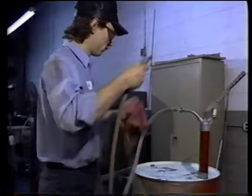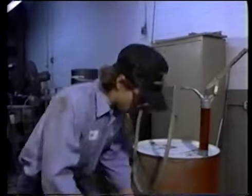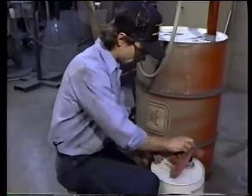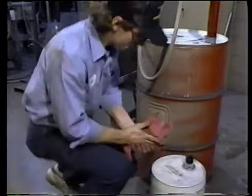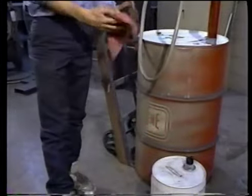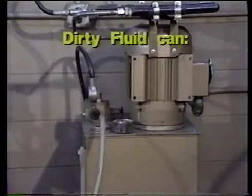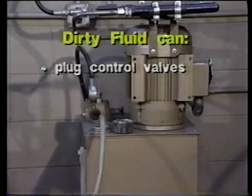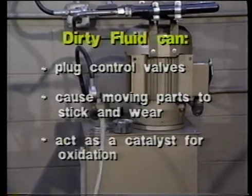When transferring from drum to drum or from drum to reservoir, always wipe off the top before breaking the seal. Make sure you use clean transfer pumps, funnels, and hoses. And check your hands before getting near the fluid. You should always filter any fluid added to the reservoir. Dirty hydraulic fluid can plug up many kinds of control valves. It can cause moving parts to stick and wear excessively, and it can act as a catalyst for oxidation.